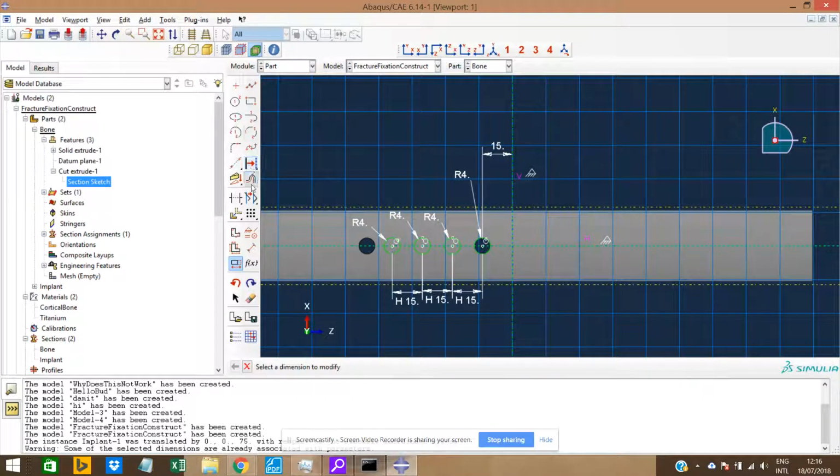Right? Oh, so the last step. I did not want to have to model that on the other side. So I'm gonna mirror them. So select type of mirror operation. I want to copy, select the mirror line. Of course, it's this one. Select the entities to mirror. By the way, use shift when you want to do control operations here to select multiple things. Not control, shift. Well, sometimes in other things like in the tree, you want to do control, but in the sketches, use shift. I didn't figure it out at first and drove me crazy.